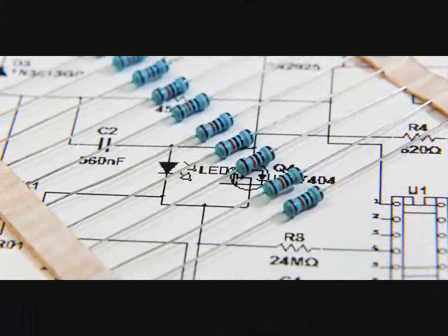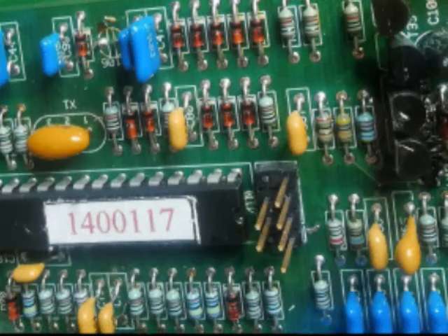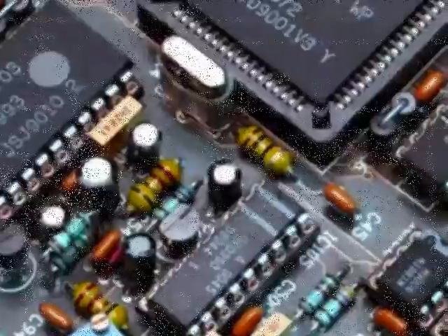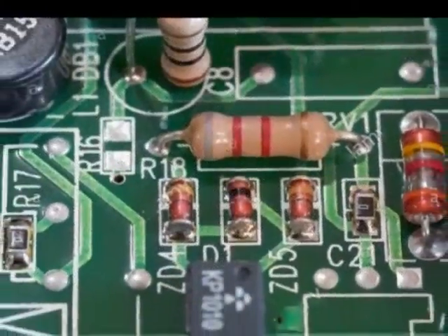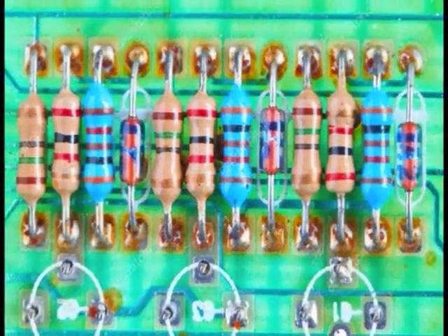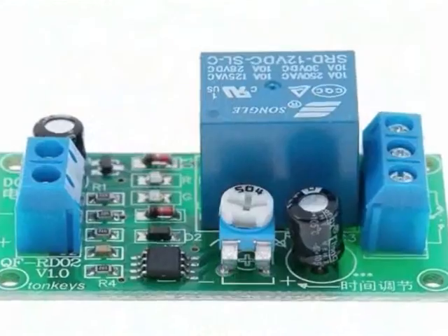Carbon resistors are used for low to medium powers. This type of resistance has a low inductance value. As such, this resistor is very suitable for high-frequency applications. But one of the weak points of carbon compound resistors is noise and instability at high temperature. For this reason, these resistors are used less in circuits that require high sensitivity and accuracy.